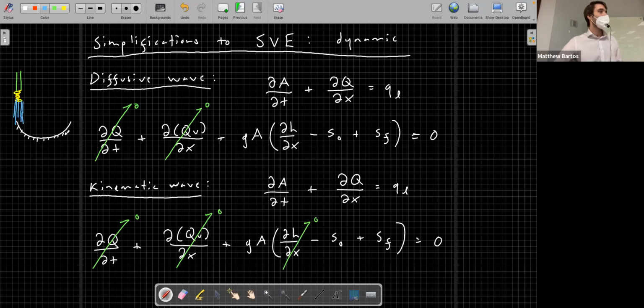In the full Saint-Venant equations, what'll happen with this water in the actual real world system, if you're shooting water very quickly from a hose into a parabolic channel shape, what'll happen with the water as it comes to this end? Yeah, it'll fly out because the water has momentum or inertia, right?